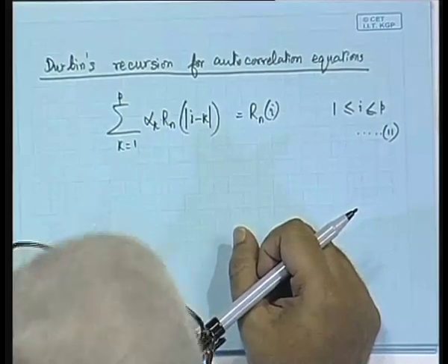So essentially it is the inversion of the Toeplitz matrix, and if we follow the inversion steps, then a very beautiful iterative methodology results, and the steps of iteration will be written in terms of the prediction error, because after all we are predicting the function using the past samples.